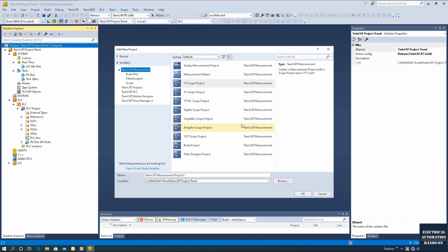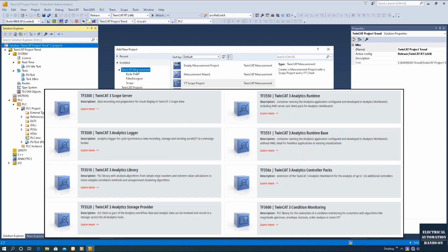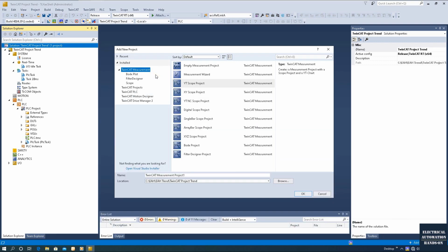More importantly, for short-term recording for engineering purposes, if you record the data for just minutes or roughly within 1 hour, it's free using this software. You do not need any license. If you need to record for a long-term run, for example months or years, for a long-term trend or curve, you need to purchase a license named the TwinCAT Measurement Server. But in most cases on site, when we're doing engineering programming or troubleshooting, this TwinCAT measurement is fully enough. This is free, and you can create the project standalone. So it's very convenient. All right, let's start.